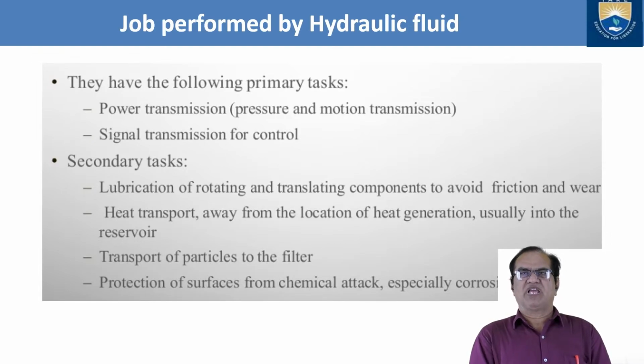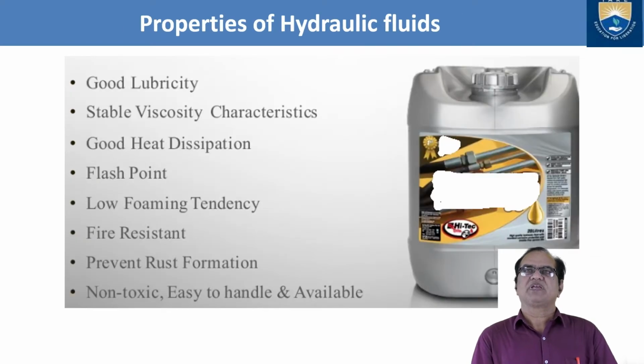Heat transport away from the location of heat generation, usually into the reservoir. Transport of particles to the filter. Protection of surfaces from chemical attack, especially corrosion. It should not happen. Properties of hydraulic fluids: it should have good lubricity, able to lubricate properly.